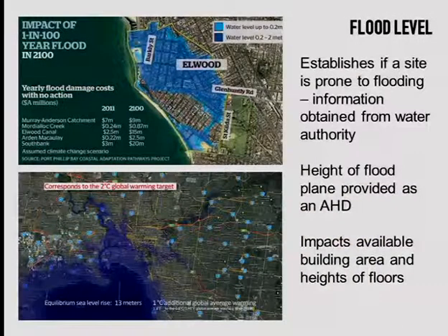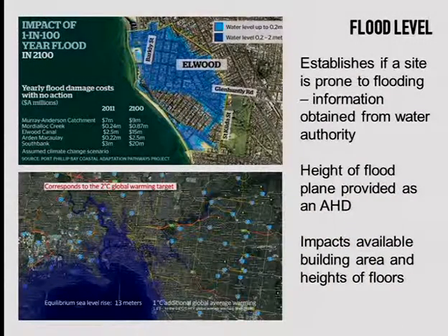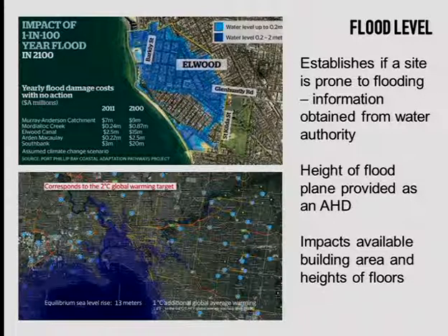The flood level. So when there's a heavy rainfall, how high will the water come up? And some areas are prone to flooding and others aren't. Now, the Water Authority a few years ago changed all the flood levels for Melbourne. Okay, so when I did a house, a couple of units in Baldwin, which is a classic suburban area where no way in the world you would think this would ever flood, they determined that the flood level now was 1 metre above the existing ground level.